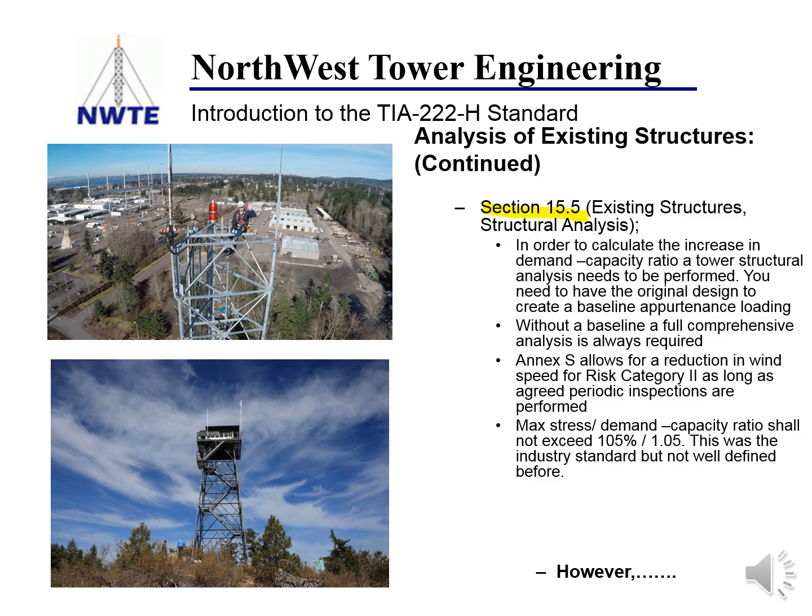It sounds like an interesting clause that we might be able to use, but in order to calculate the demand capacity ratio, you really need to carry out an analysis of the structure, and you also need the original design to create a baseline to compare against. So without a baseline, a full comprehensive analysis is always required.